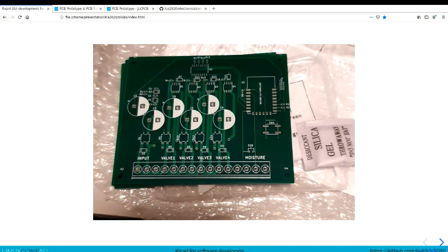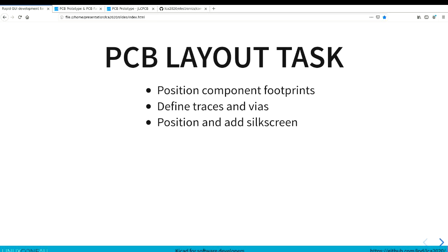You can see it's got the green solder mask. It's got a HASL coating, so it's been dipped in solder. And you can see the white text of the silkscreen. The traces are the lighter green, where the copper is still present. That's the wires running across the board. So that's what we're going to produce.